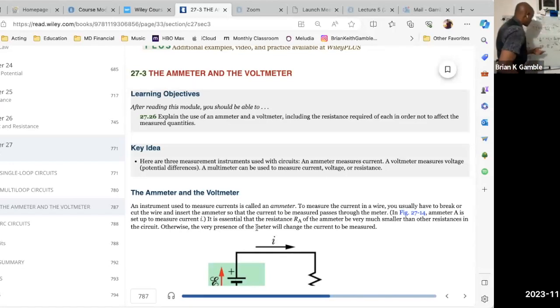Which indicates that the current is just so, if I take the derivative of that, then that minus sign is going to pop out. And so I'm just going to have I of t is equal to minus E over R, e to the minus t over RC. So these two solutions are for a discharging capacitor.